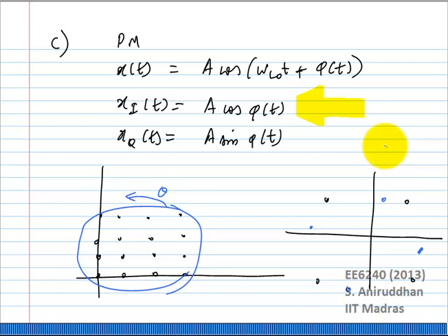So all of these things will have to be guaranteed on both sides. Okay, so obviously both phase and frequency error are a problem. Now part of the frequency error can also be taken into account, not through a pilot signal, but through something called a preamble in the signals. But you can take care of it through coding also. Just wanted to let you know.